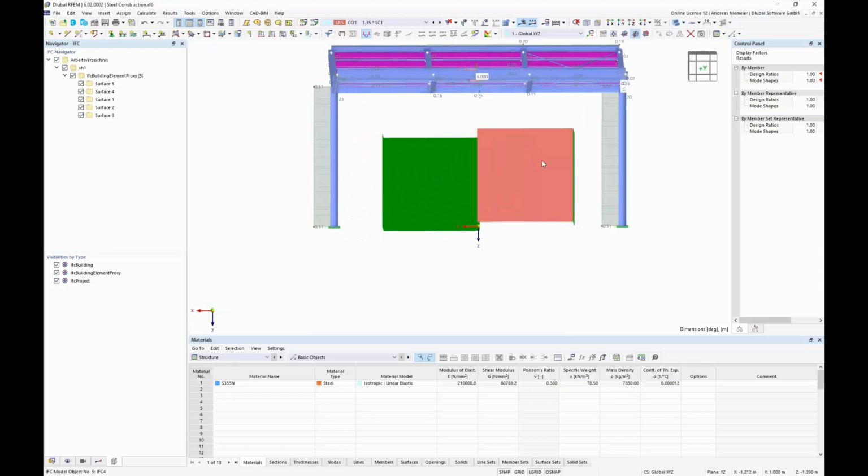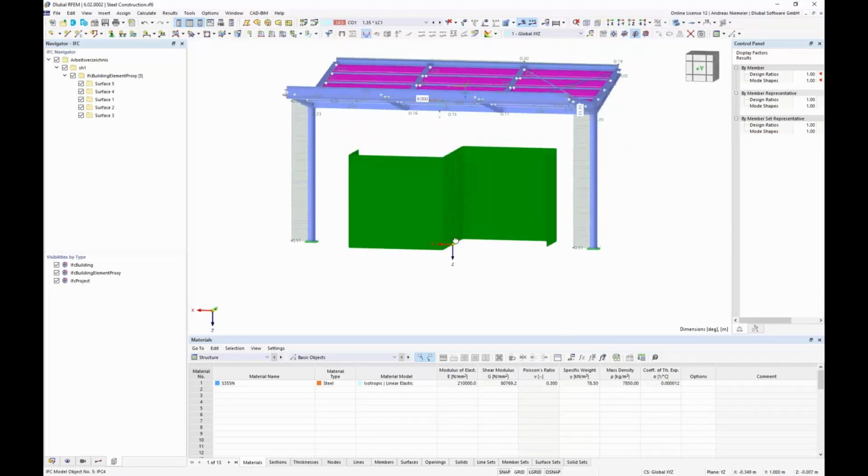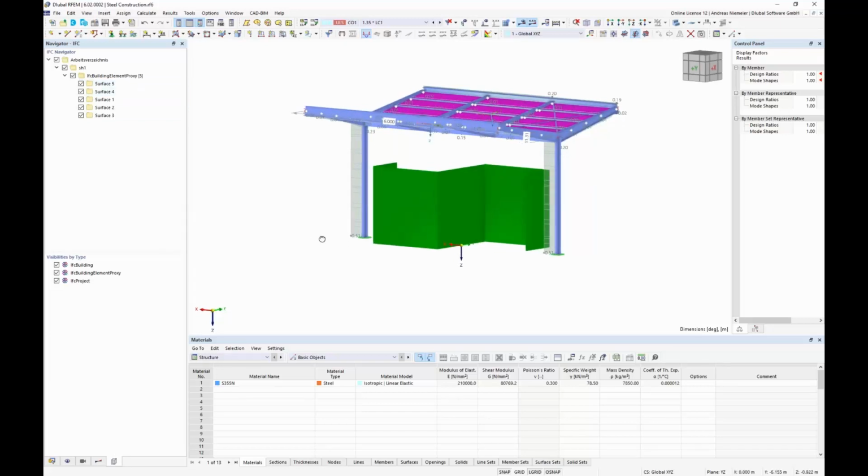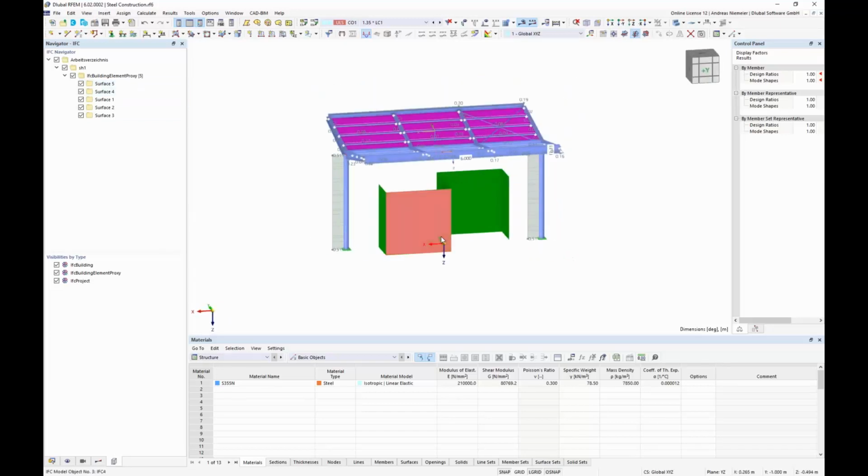And it's not a surface, then, it's an IFC model without stiffness. We get it here in a specific BIM navigator where we can also deactivate and activate some surfaces, but this model could be used for our wind. And as mentioned before, we have mesh settings where we can rule which elements will be moved into the wind tunnel.